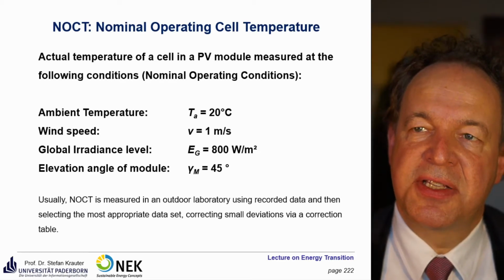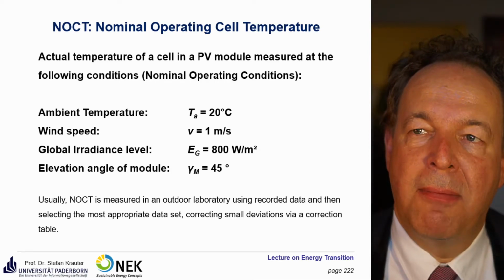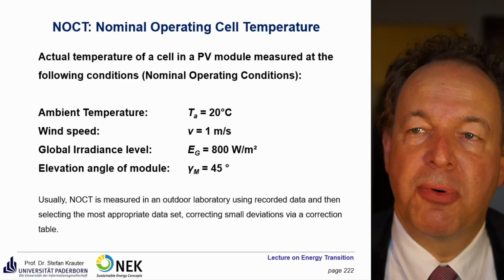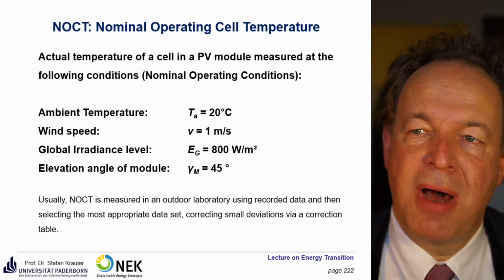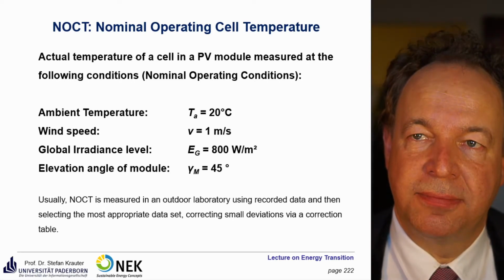This NOCT is more realistic than the STC conditions, but unfortunately industry doesn't take this because the values are much lower, as you see already by the irradiance level. So you have at least 20% less performance and power output. So the industry always prefers the STC conditions.